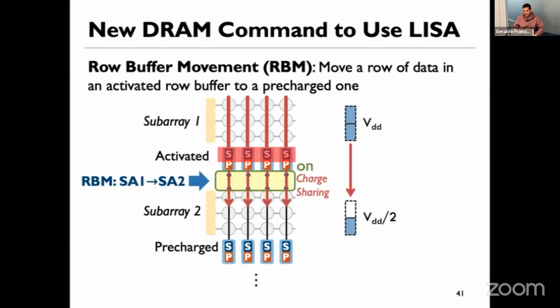By doing this connection, the charge sharing is going to start happening between the bit lines in this local amplifier and the bit lines in the precharged DRAM subarray.